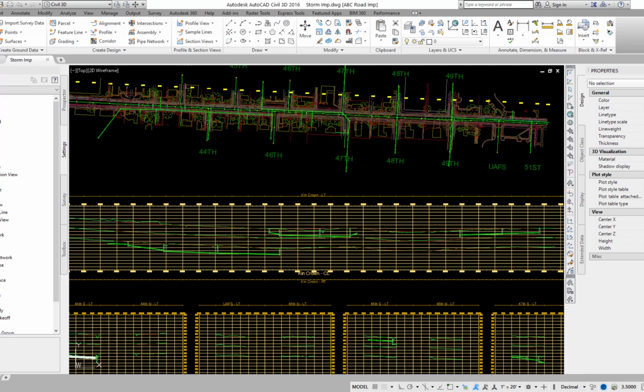I also use a spreadsheet I created for the hydraulic analysis of a storm drain system. I start from downstream with a known or assumed hydraulic gradient at the pipe soffit elevation. I proceed upstream computing the hydraulic and energy gradient at each upstream structure. In a huge majority of the cases, it is immaterial as to the actual flow characteristics within a pipe. The only concern is whether the size of a pipe is adequate to handle the design flow. As such, I make my hydraulic calculations simple by assuming full pipe flow.